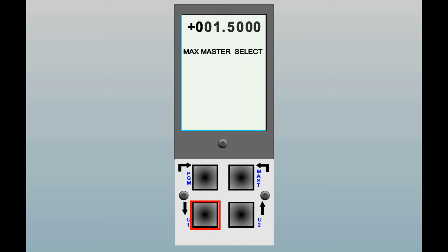Ignore the colors of the bar lights, as these can be configured independently. And be careful not to mix up the min and the max masters. If you can't reach your required master size, or if it is too small of a spread, then you'll need to change the mode gain selection and press Enter to store this in memory.